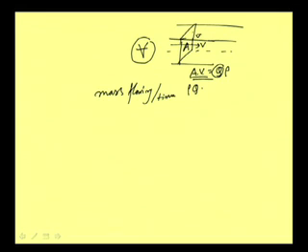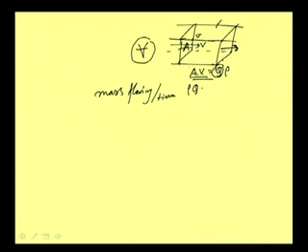through this section. When we talk about conservation of mass, the mass flowing through this section and the mass flowing through a downstream section will be the same. What mass we are having here, what mass we are getting here will be the same, unless there is a lateral flow from this side or that side. That is the conservation principle. So rho Q at section 1 is equal to rho Q at section 2.